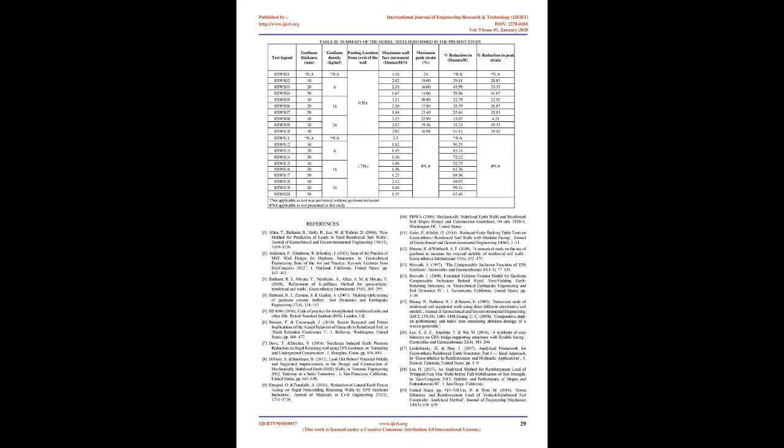This should not be the case when a rigid panel facing is used for construction of the geogrid reinforced soil walls. Geofoam inclusion behind the reinforced zone does not change the pattern of wall face movements significantly, but shows a significant decrease in wall face movements with increase in thickness as well as decrease in density of the geofoam. This is mainly due to the allowed deformation of reinforced soil towards the backfill.